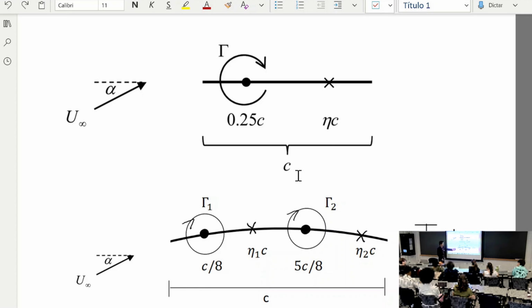Which is really, there is a boundary layer. The boundary layer is very thin at the leading edge. It becomes thicker and thicker toward the trailing edge. If you have faster flow around the trailing edge, the boundary layer is going to separate. But if you have very fast flow around the leading edge, it's much less likely to separate because the boundary layer is very new and very fresh and is much harder to separate on the leading edge.